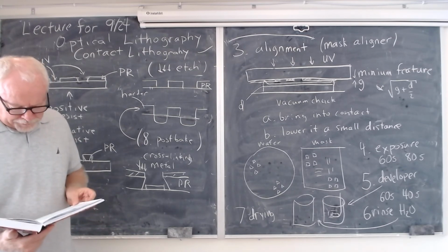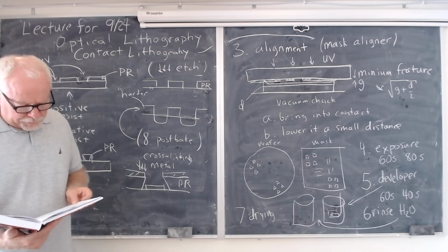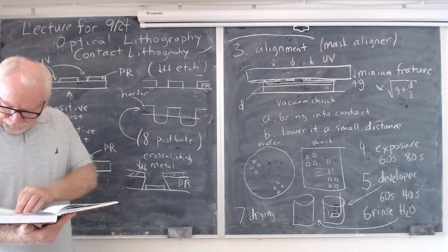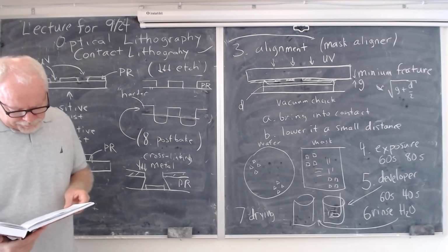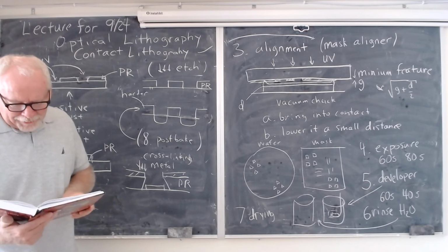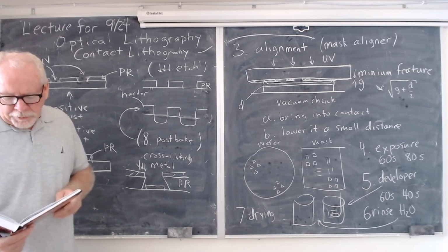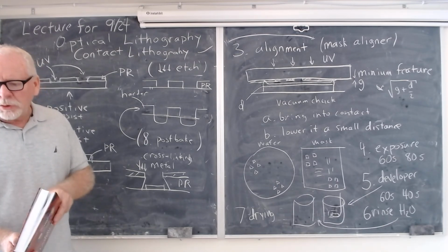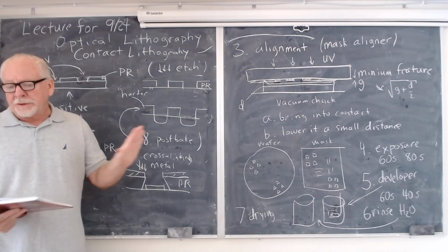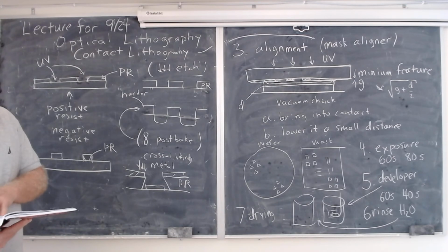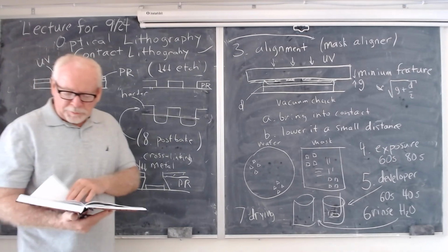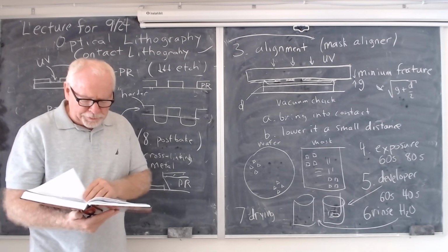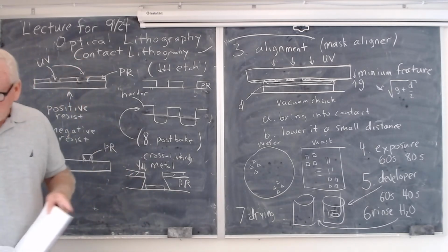The last thing here, photoresist stripping, is usually done in acetone. It must be removed. It's always acetone. I mean, I guess there are other methods. See, this is where he's jumping back and forth ahead. Just for now, you use acetone. Okay, that's how you strip the resist. There can also be plasma processes, but we haven't covered plasma processes, so just consider that it's going to be acetone.